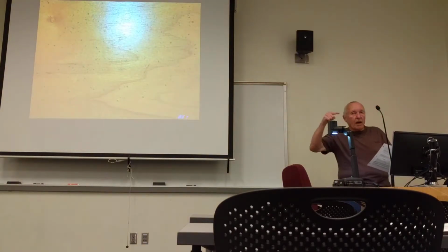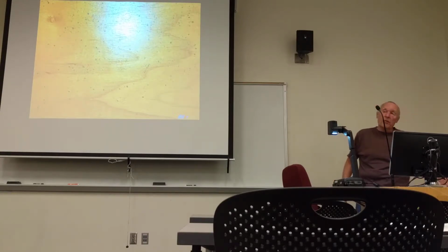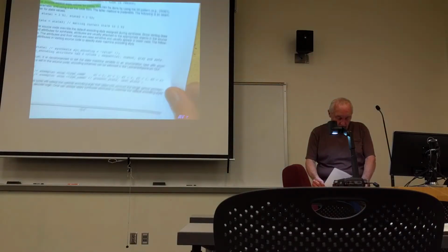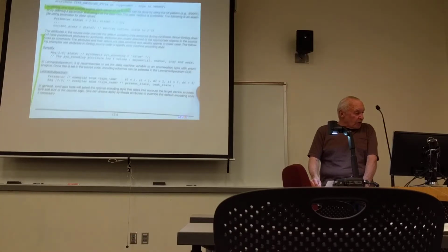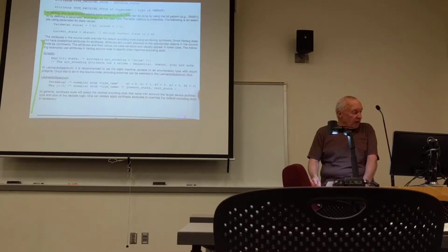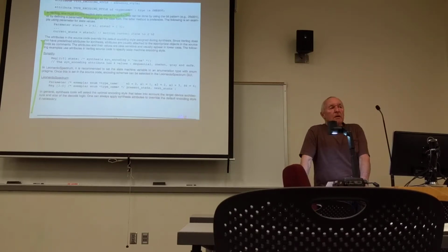Again, design before coding, read the synthesis guidelines before you write your first line of code. This is something I wanted to show you. They're talking about for Verilog providing explicit state values. The question is, how would you tell the synthesizer you want one-hot encoding or some other encoding method for your finite state machines? Well, there's 2 ways.